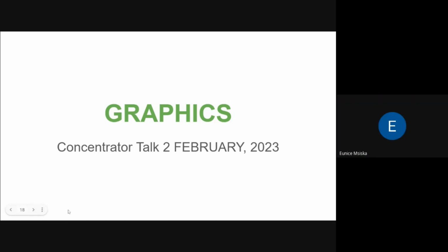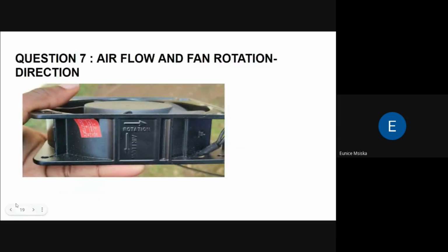Okay, thank you. Oxygen concentrators make use of compressors to generate pressurized air for the purification process. Compressors tend to experience a rise in temperature as they operate, so they need a fan to cool them off when the temperature rises. The DeVilbiss 525 has its fan mounted beneath the compressor to aid in cooling it when it gets hot. A defective fan will cause the thermal switch connected to the compressor to open the circuit and hence turn the machine off due to the rise in temperature.